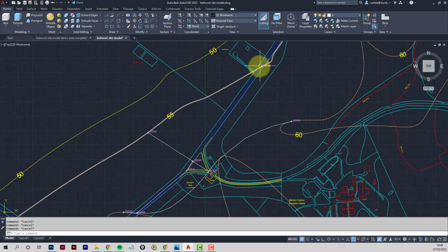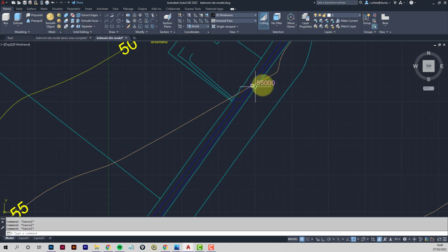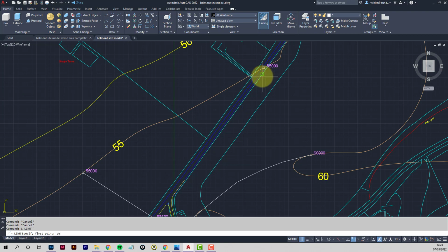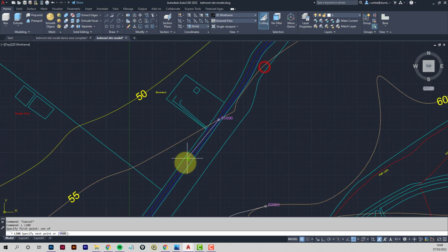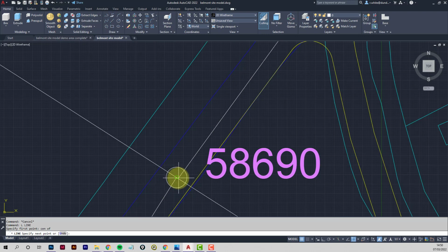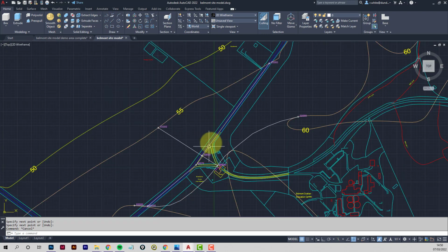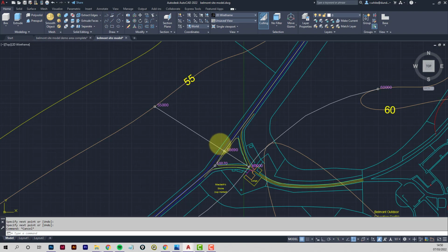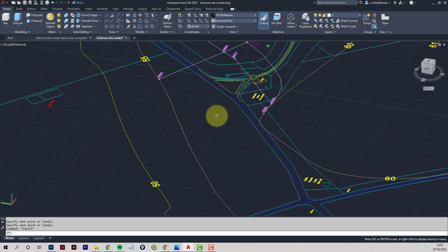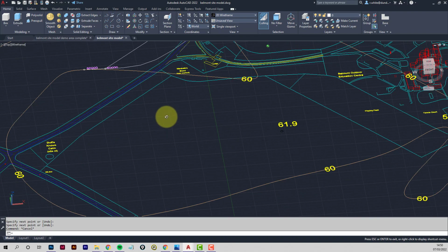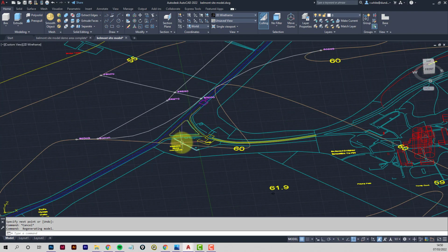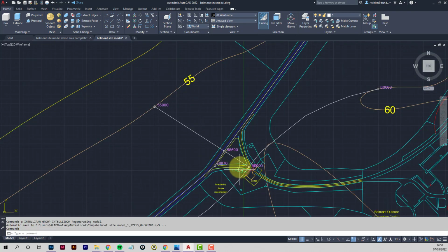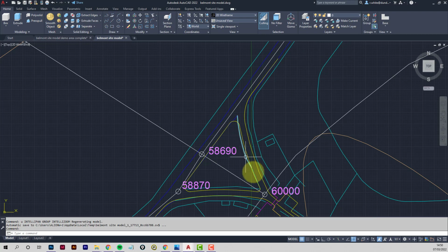Okay, now I've got a much bigger spine that we can put in here. We've got the contour crosses the highway at this point, so that's another spine that we can put in right the way back to there. Check this once in a while just to make sure everything's behaving. So just flip it over into 3D view, just make sure there's no lines dramatically dropping down to the ground. It's very easy for that to happen when you're working from the top down.